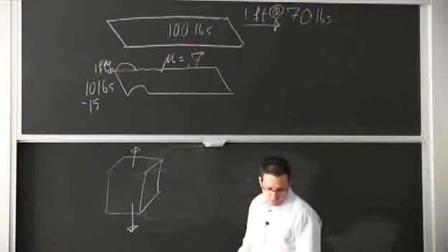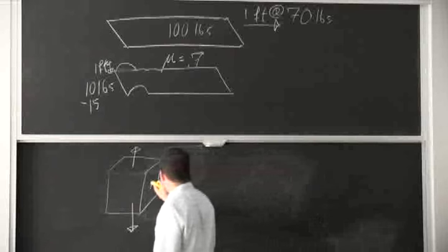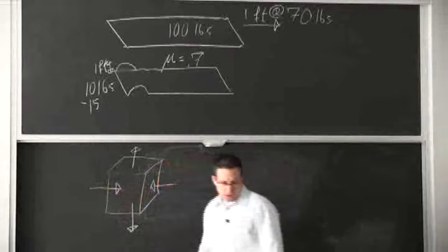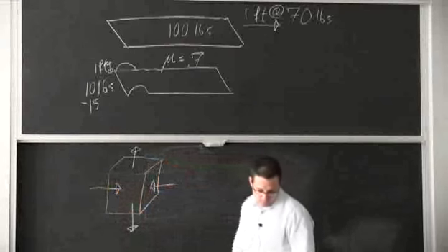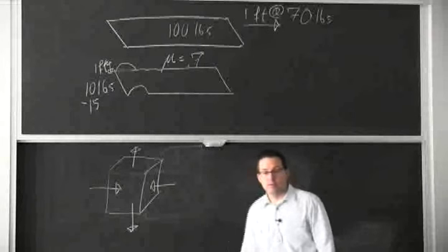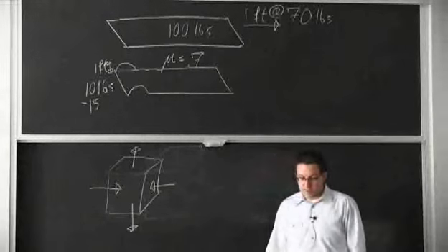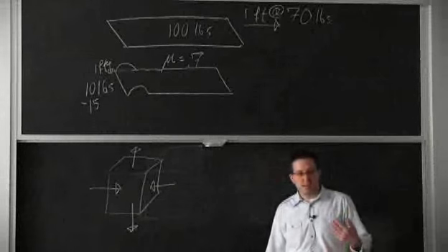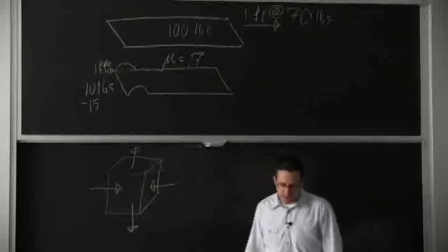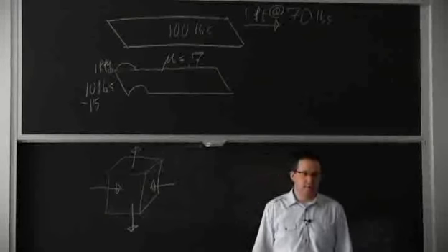And if I go and apply a compression of the same amount in the other direction, we're going down on that curve where one of the stress components is equal to the other. So we're down here, it's pure shear. So it will take less force, less stress if I add a compression in the second direction to create yielding.